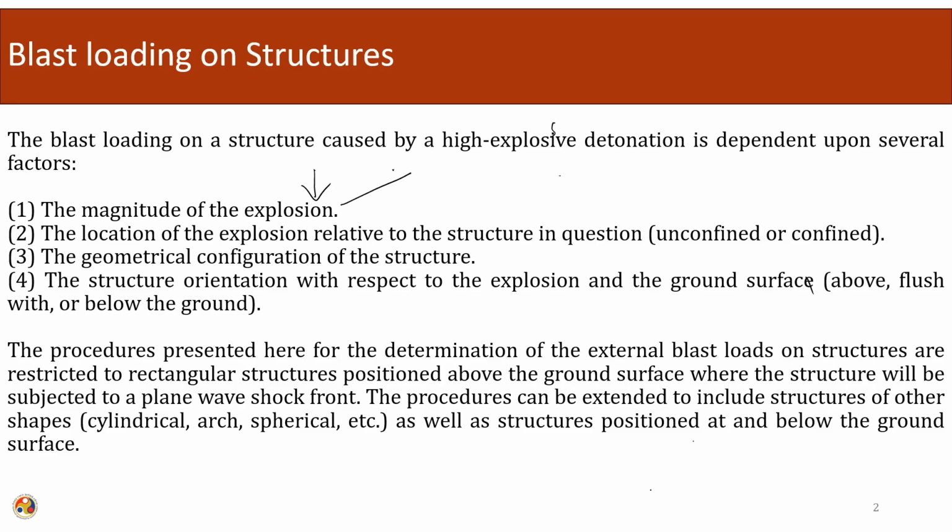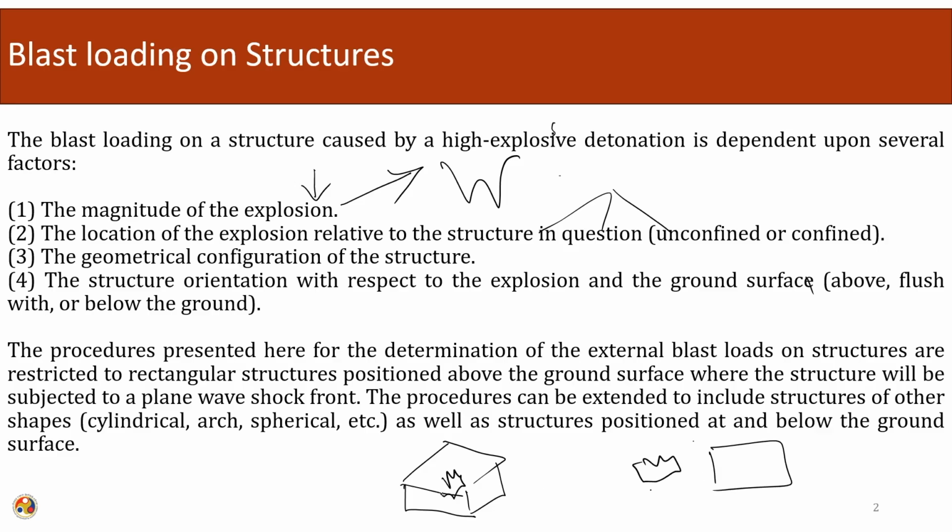It depends upon the magnitude of the explosion, meaning the weight of the explosive. It depends upon the location of the explosive relative to the structure in question. This has some parts. One is whether the structure is confined or unconfined, that is, whether the blast is occurring in a confined structure or in an unconfined structure. So we have seen that we categorize our blasting into two types, confined and unconfined, based on the location of the explosion relative to the structure in question.